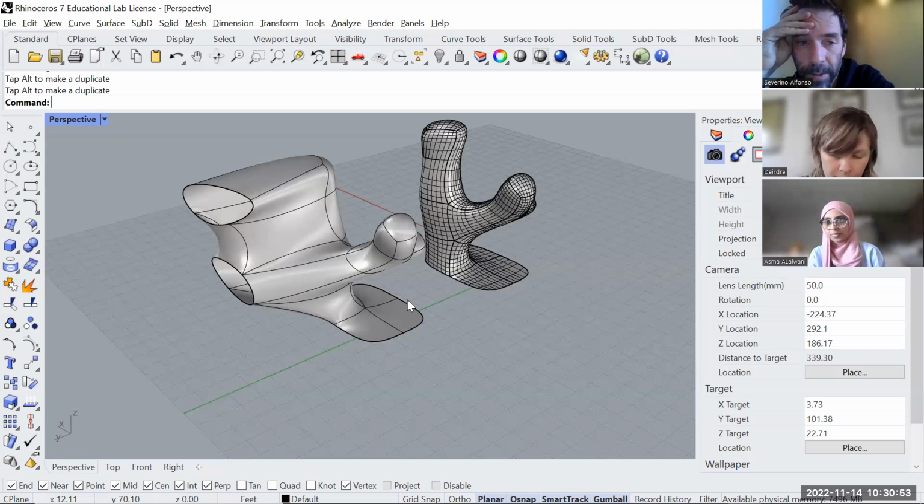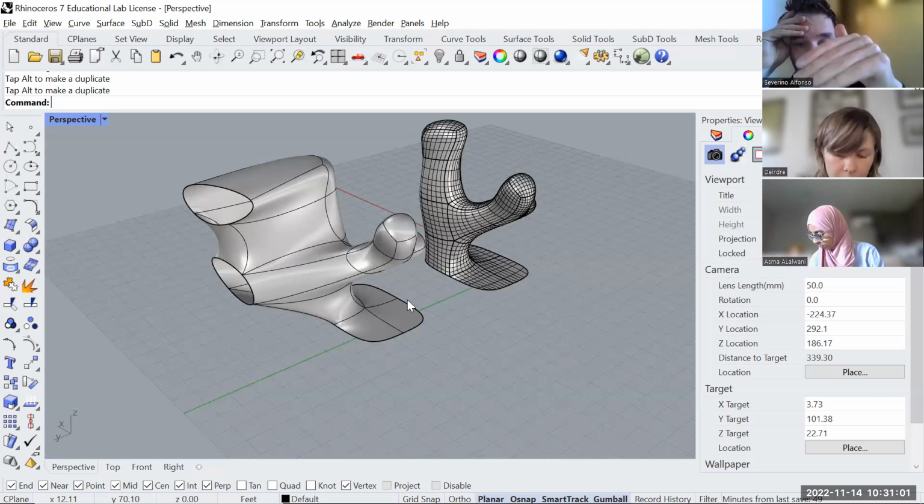But so again, step one, I would say, in Revit, select floors. I would probably think of what is that opening in the second floor to make sure you can connect the whole flow. Once you have that opening, take only the floors and extract or export the floors to Rhino. Bring them at the same scale.